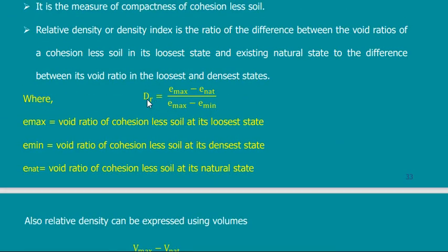So it is relative density related to compaction of soil, because we said that the relative density is related to E. E is void ratio. We said that sand is affected by void ratio, and clay is affected by water content. So if I have a property that depends on E, it mainly is related to sand and sandy soil.